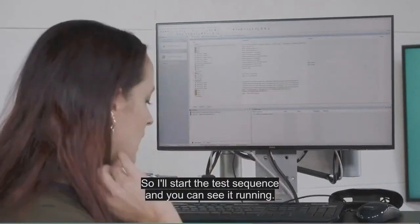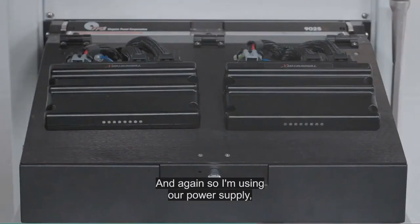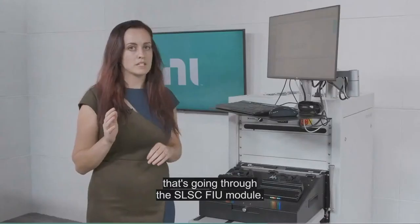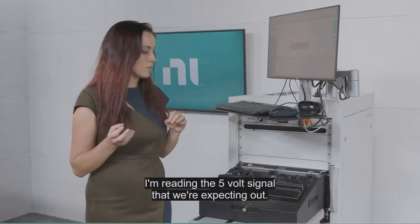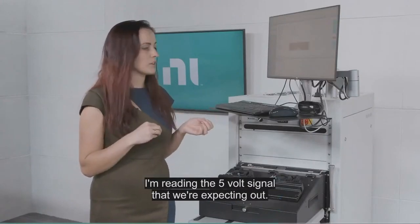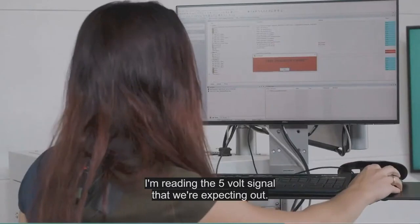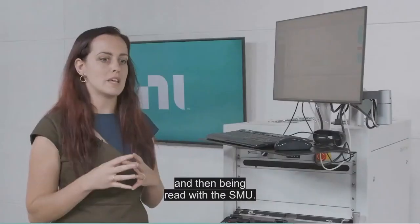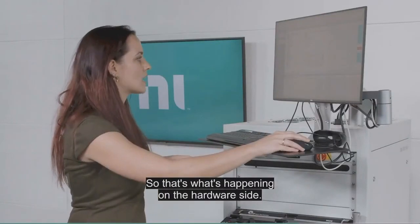You can see it running, and again, I'm using our power supply to power the units. That's going through the SLC FIU module. I'm reading the 5-volt signal that we're expecting out. It's going through some switch matrix and then being read with the DAQ. So that's what's happening on the hardware side.